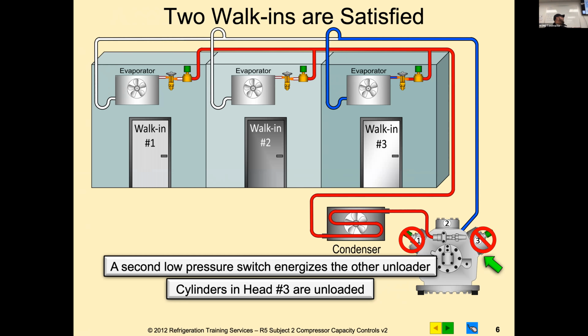So if the compressor goes down, all 3 coolers. Yeah. Why don't they run separate? Well, they do usually. Where we see a lot of unloading is in rack application parallels. So you'll see on bigger systems though where they have 2 compressors or 3. Anytime you're using staging, a lot of times your staging will also have unloading. So what we see a lot more now is more variable speed, which we'll get into in this class.